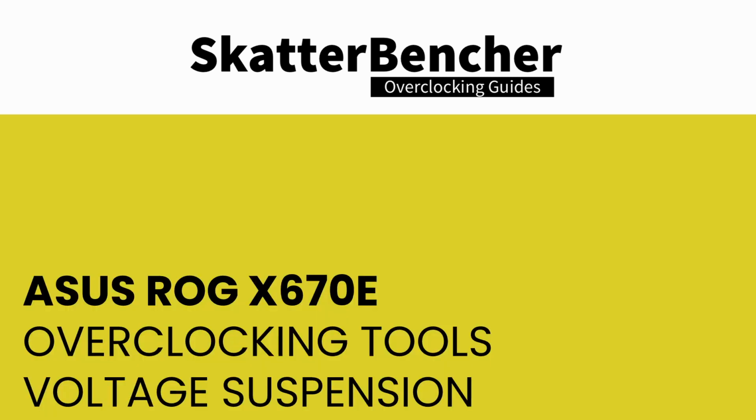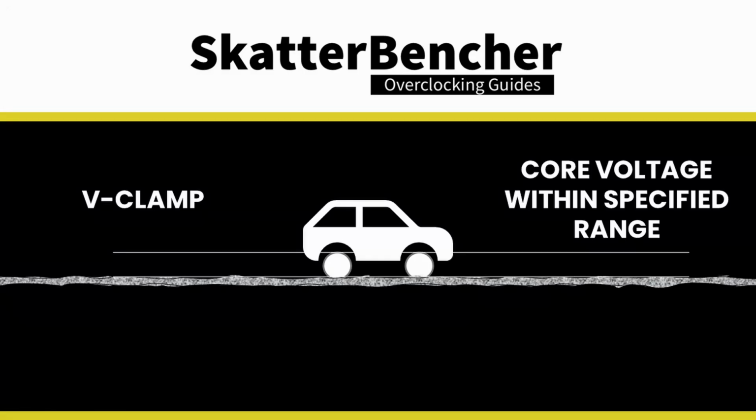Voltage suspension is again not a new feature, as it was already present on the Crosshair 8 Extreme motherboard. While it's a very advanced feature, I would say, I still find it particularly useful, especially when tuning for an all-core overclock with Precision Boost Overdrive. The term suspension is akin to a car's suspension, though I prefer the more technical term V-clamp.